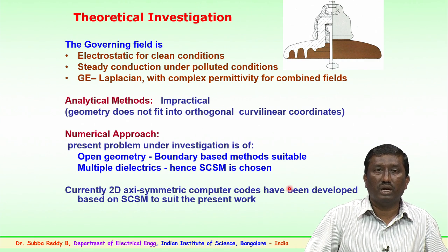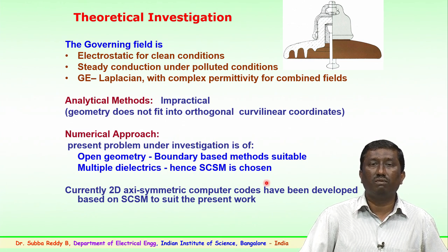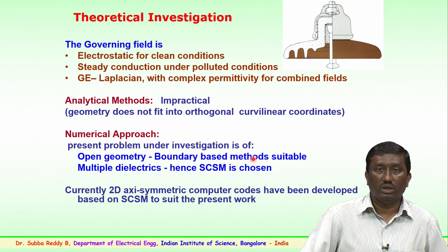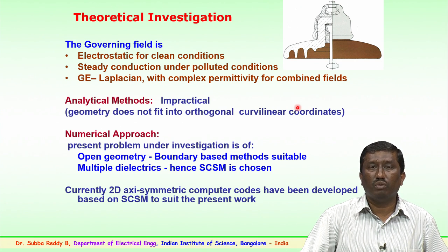So, we have carried out theoretical investigations where we have assumed the governing field as electrostatic, particularly for clean conditions, and steady conduction under the contaminated conditions. For the theoretical investigations, we have used the governing equation as a Laplacian with complex permittivities, particularly for the combined fields. Simulating the method or developing a model using analytical methods is impractical because the geometry of this insulator